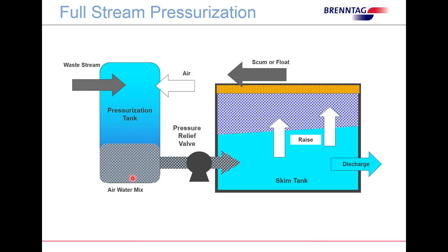I'm not a big fan of these units, and the reason being is because you're pressurizing the incoming wastewater, this tank can oftentimes become fouled, causing problems with good air-water mixture, but just causing some real basic problems with making this a very dirty tank. But this is a fairly common full-stream pressurization unit.